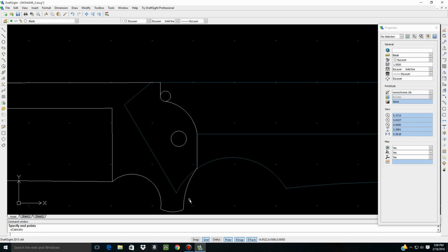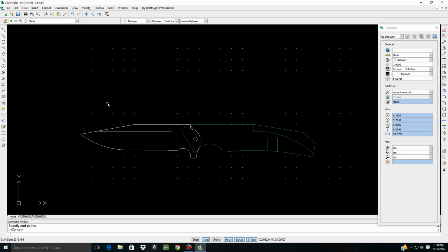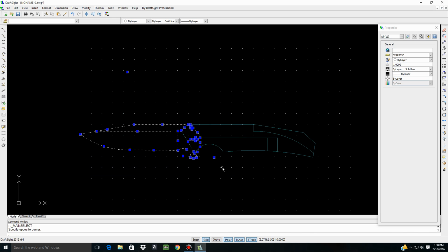Of course, since we moved this, now we also have to move the handle. You can leave it like this, some guys do. I like to go the little extra step and clean that up, but that's not important right now. We could always fix that later. So now that we have the lockup correct in the open position, let's just make sure everything works in the closed position again. So we'll highlight the blade, go to our rotate, make sure E-snap is on, and grab that center point.